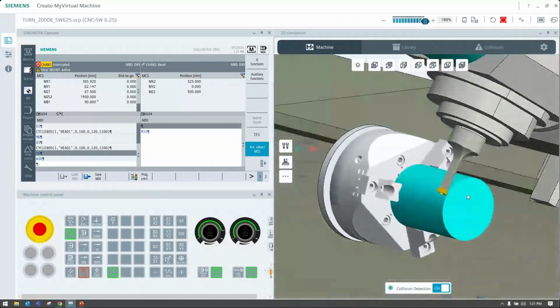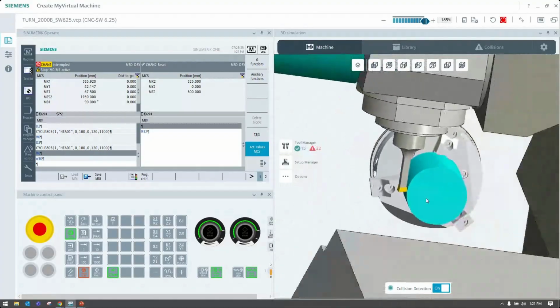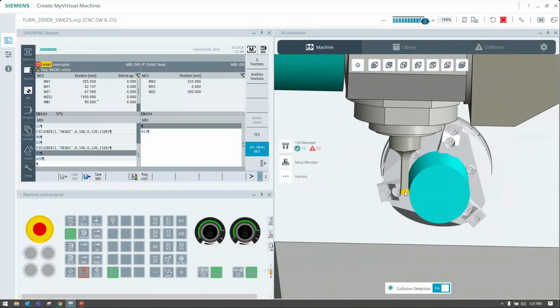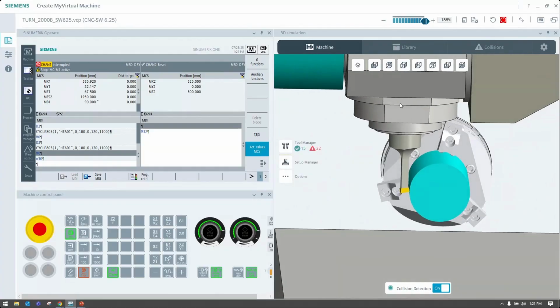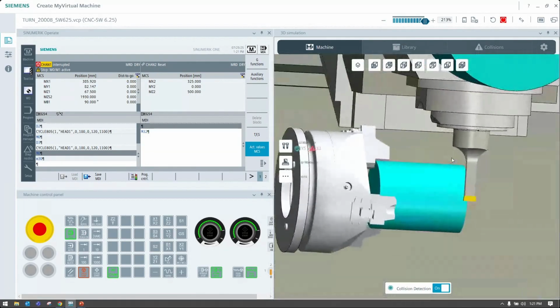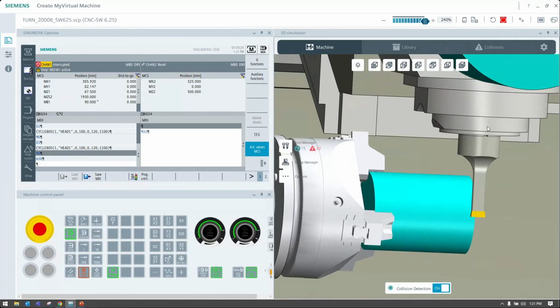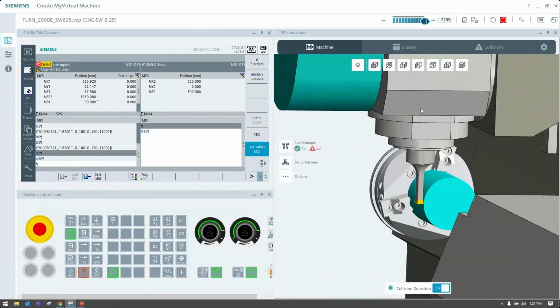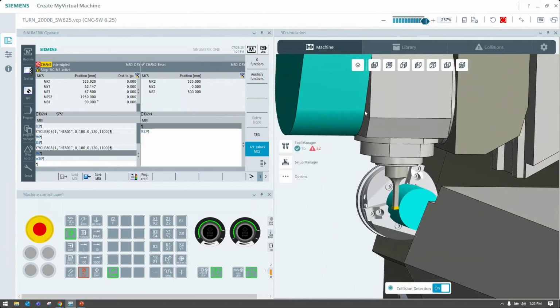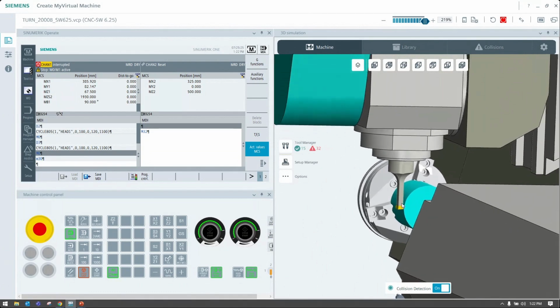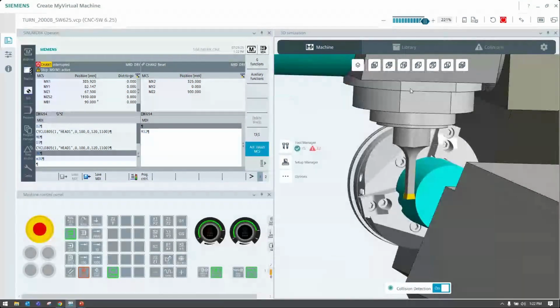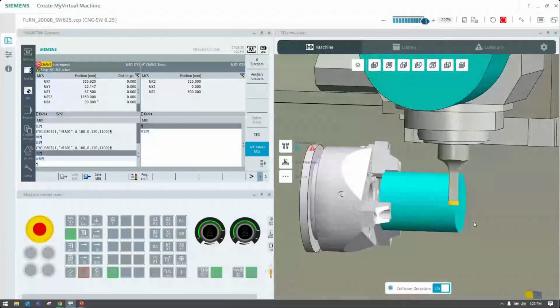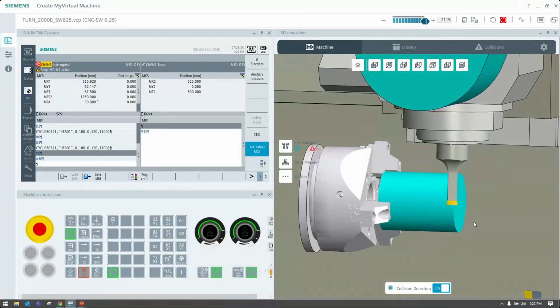And then talking about cutting forces, right? If this is spinning, the forces are going up, versus if we were on a turning tool, the forces are going this way. So this is going right up into the most rigid portion of the machine, because this is being held right here, right? So all the forces are going this way. So this is, I think, going to really showcase heavier cuts as well as being more stable.